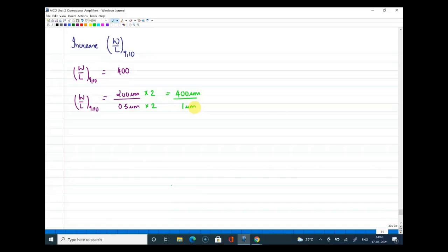So what is the difference? We have increased the length of 9 and 10 by a factor of 2. That implies that lambda is reduced by a factor of 2. So I need to recalculate the resistance R0 of 9 and 10 as 1 divided by... Previously your lambda value was 0.2, since it was a PMOS device.